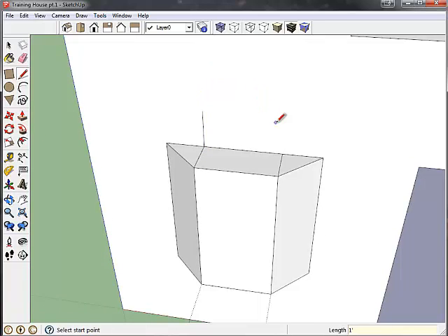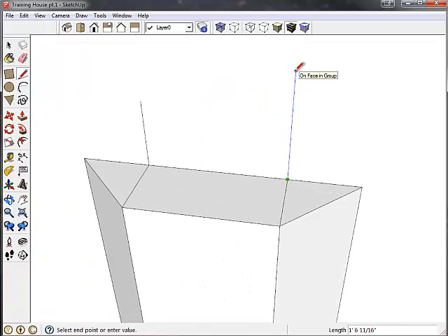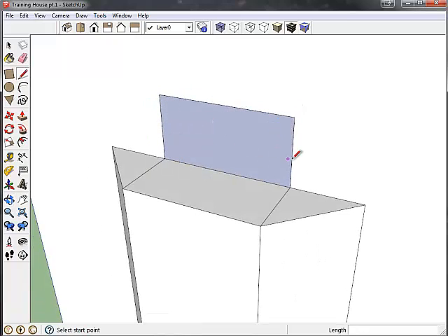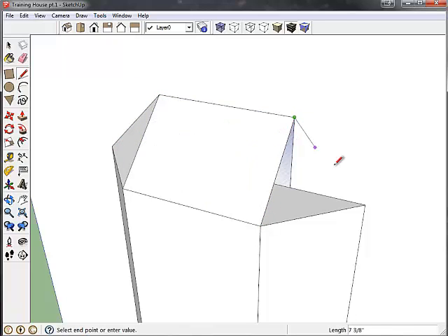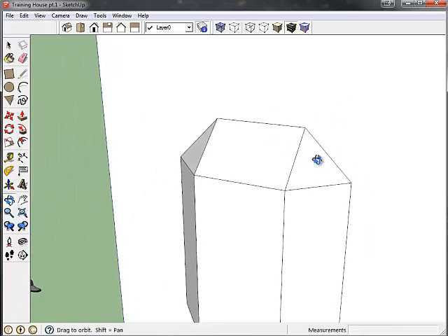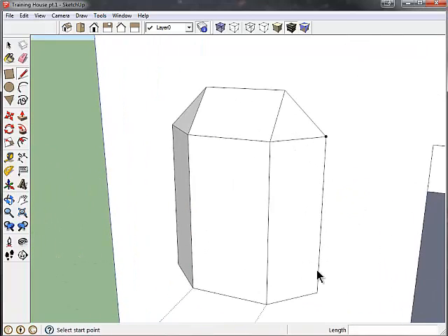Always extend your lines a little bit further than they have to go, so you can tell that it's blue in color, and then enter the distance, or simply infer as you've done before. With these lines we're done with, and the rectangle drawn, delete, delete, connect your edges from here to here, here, and to here, with your roof shape that should look like that.